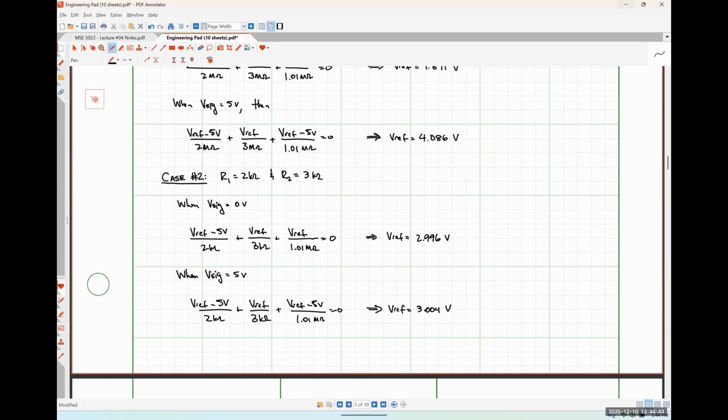So 5 volts over 5 ohms of resistance means that we're going to be drawing 1 amp of current. And so that means that that 2 ohm resistor is going to be absorbing 2 watts of power, and that 3 ohm resistor is going to be absorbing 3 watts of power, which means we need very large, beefy, and expensive power resistors.